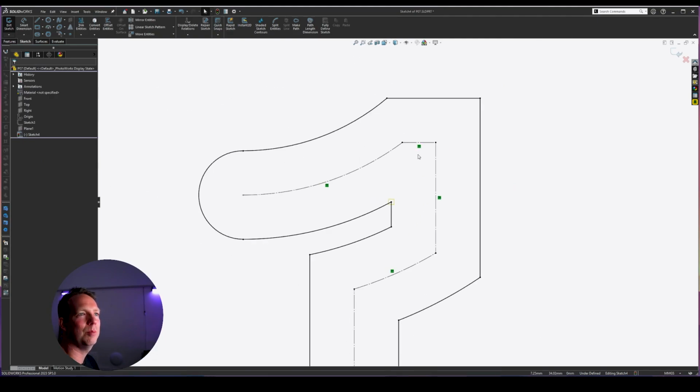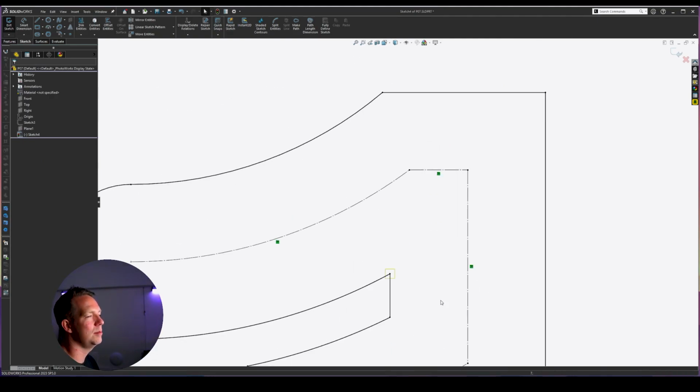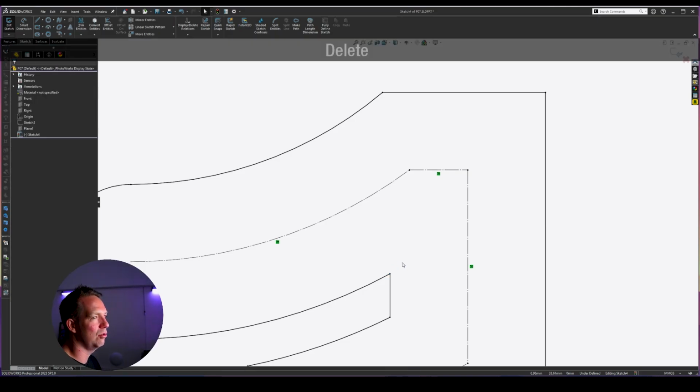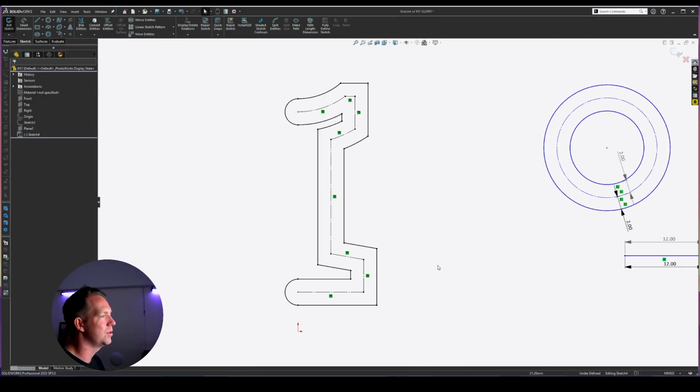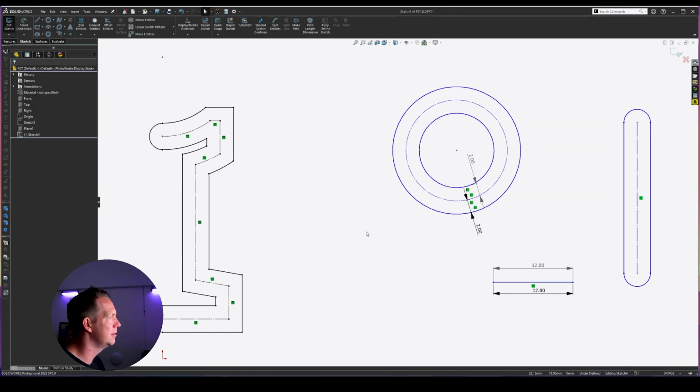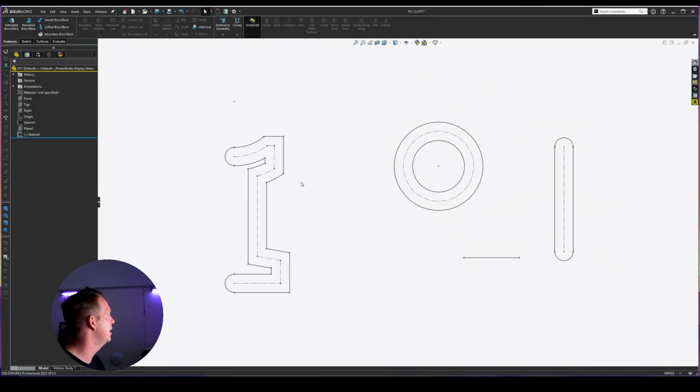When you see this kind of yellow box, my simple recommendation is draw a selection box over the top. It's going to select that line that is actually created there, which is too small to see. We can hit delete, and it's going to remove it. And then I don't have an error. I'm sorry I can't give you any more accurate detail on that issue, but that solves it. Okay, and that is how to use offset entities.